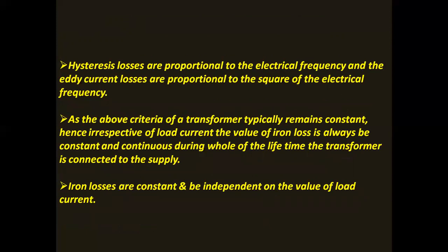Hysteresis losses are proportional to the electrical frequency, and the eddy current losses are proportional to the square of the electrical frequency.